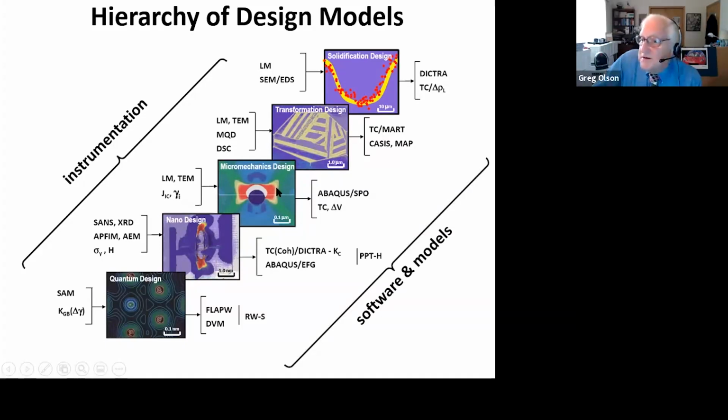So these are really the three disciplines that were integrated in this approach to meet performance goals. But equally important is to constrain the processability of a material, and that's a role for the CALPHAD-based materials science models of the solid-solid phase transformations and the liquid-solid phase transformations, both of which are scale dependent in terms of the size of heat-treated components through the size dependence of heat transfer.